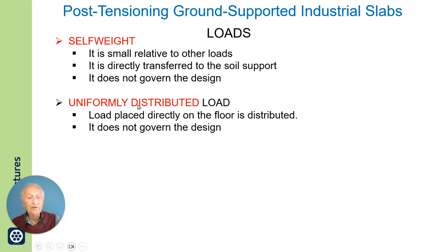Now, uniformly distributed load placed directly on the floor is distributed. Again, this is something which does not govern the design. The magnitude of it compared to the allowable soil pressure is pretty low.